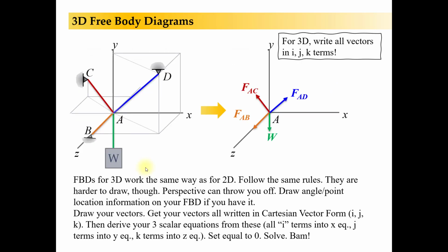3D free body diagrams. Okay, this is really the exact same thing as I said before. My 3 rules are: you keep the part you're keeping, you get rid of the parts you're getting rid of, and at any cuts, you replace the parts you cut away with the internal force vectors. Here we're going to take a free body diagram of particle A, and you can see here's my free body. I now have tension forces all acting away. There could be compression forces, but right now we're keeping it simple with tension forces.